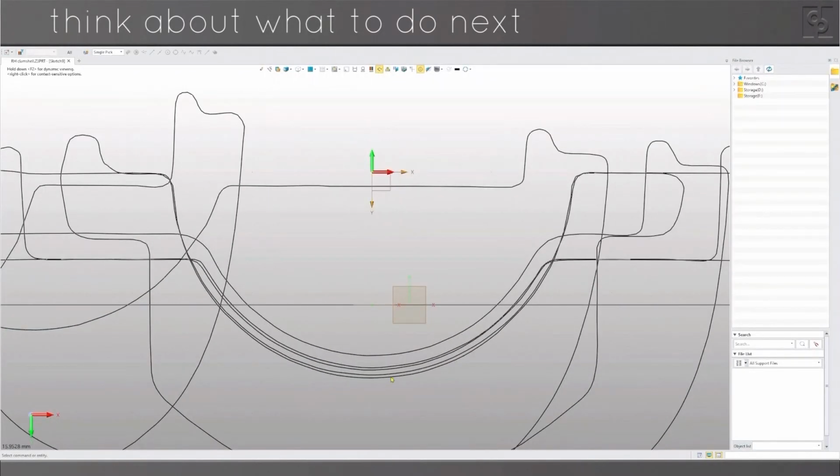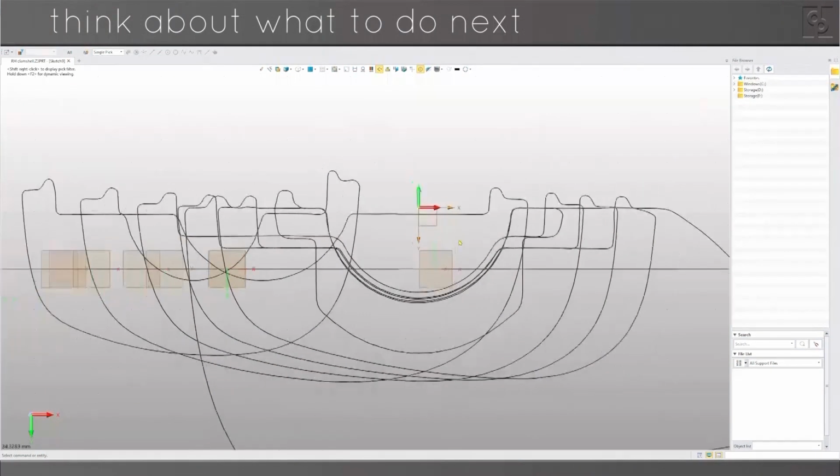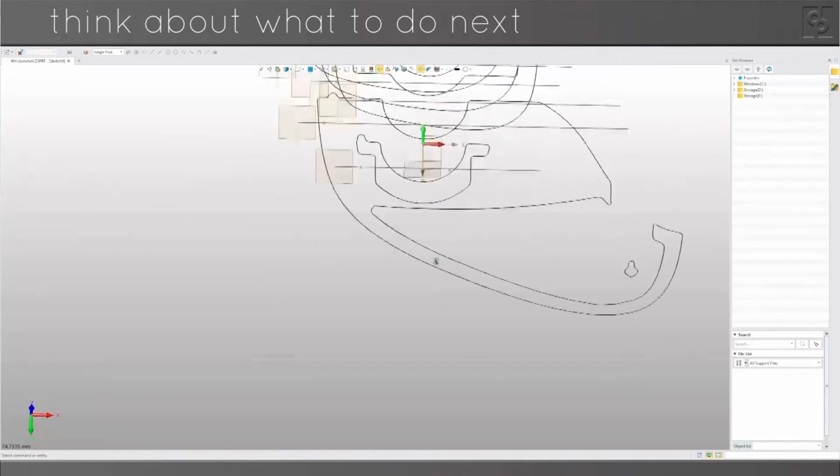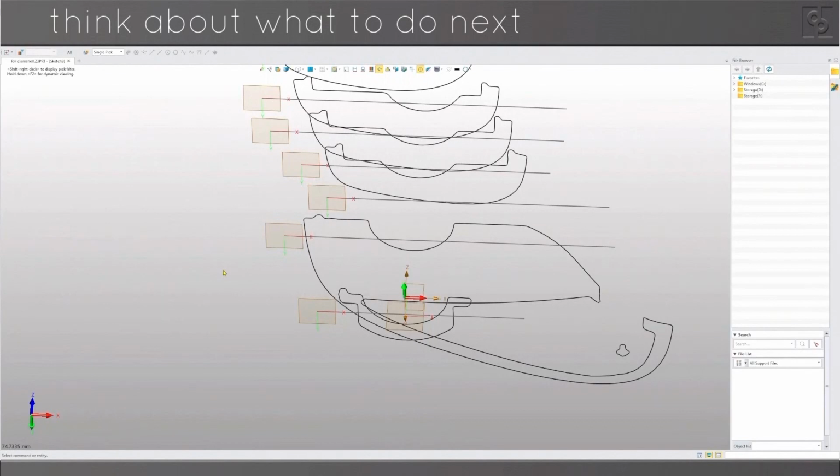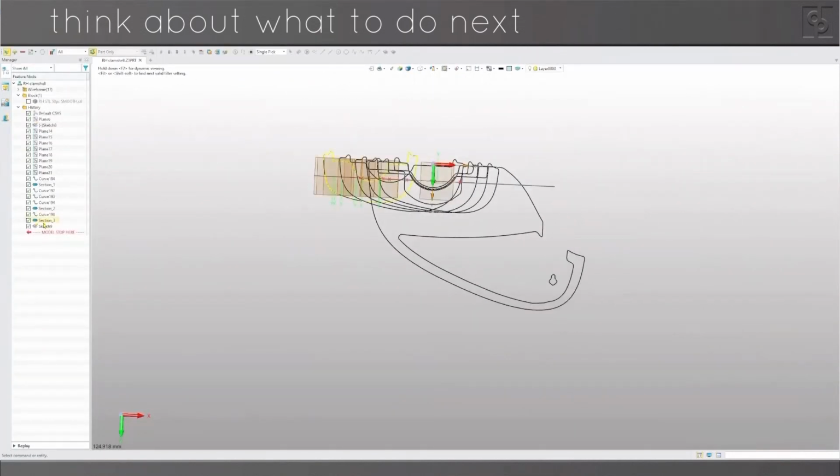So I'm not going to make an individual cutout for each rib because I know that they'll be misaligned with each other. And that's because the molding that I scanned isn't perfectly straight. Actually, those features mate onto a shaft, which is a separate component, which I know is straight. I've also modeled that. So I'll cut these semicircles out with the shaft at a later stage. And for now, I'll just make the rectangular sections of the ribs in preparation for cutting them out later.